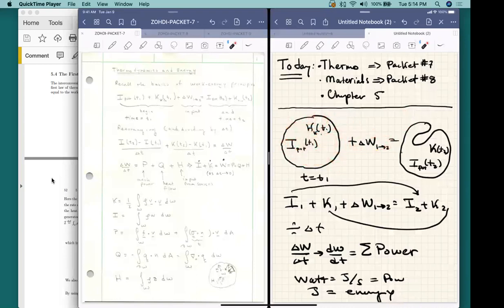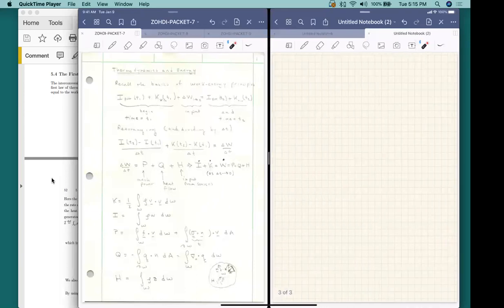So all of this stuff together, when we add them together, is going to give us the power equation. And in its simplest form it looks like this, but it's going to have many different pieces to it. So let's write this out explicitly and then start to explain exactly each of the components. So we have dW/dt is equal to the mechanical power. I'm going to separate that into several different pieces.